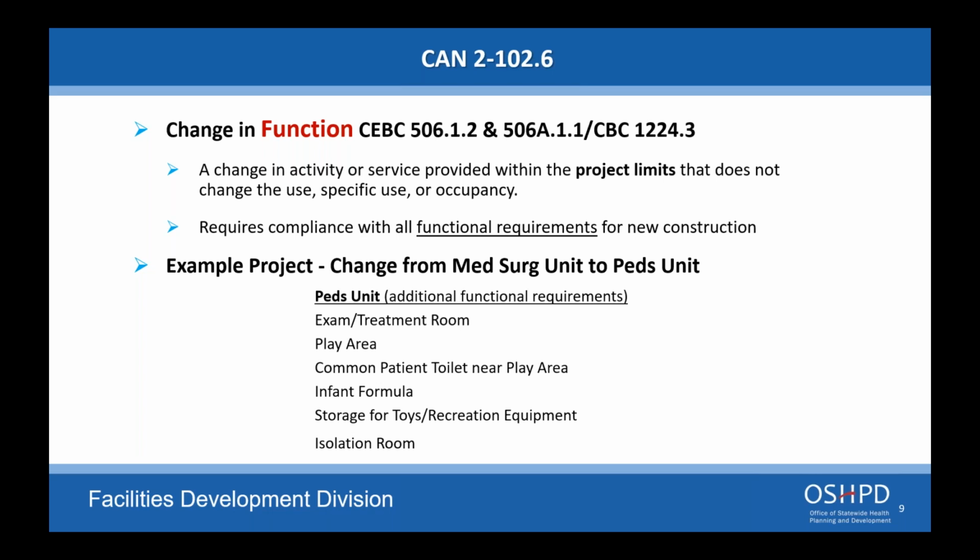Great, thank you. We have a couple more questions. We have a little over 5 minutes left, so we're doing great on time, and we're nearing the end of the questions. So the next question we have here: in a cosmetic-only restroom upgrade, wall tiles will be removed and replaced along with wall-mounted accessories. In-wall backing may be relocated. Will this require a permit? Yes. It's no longer cosmetic once you're opening up the walls and moving things around. So yes, it would be a project.